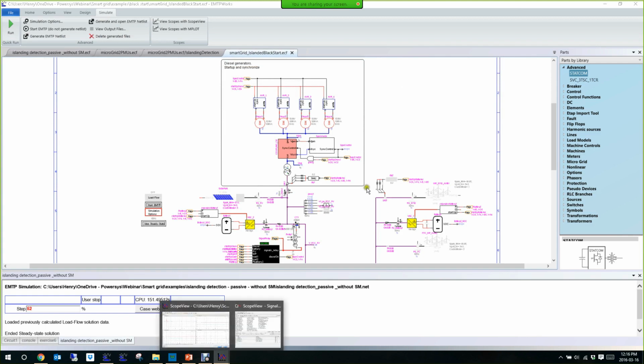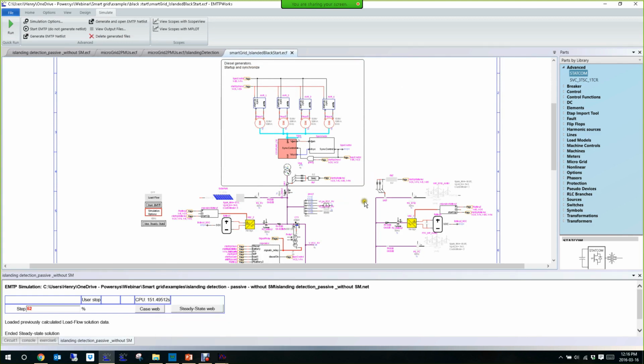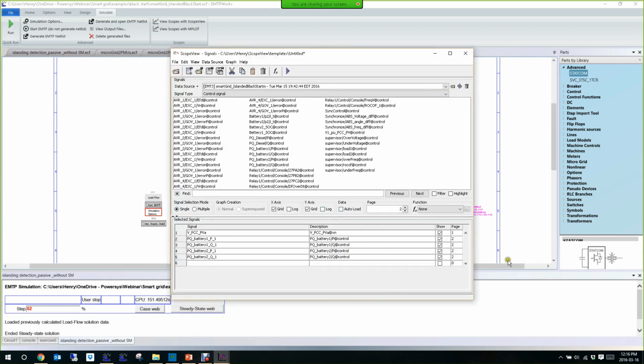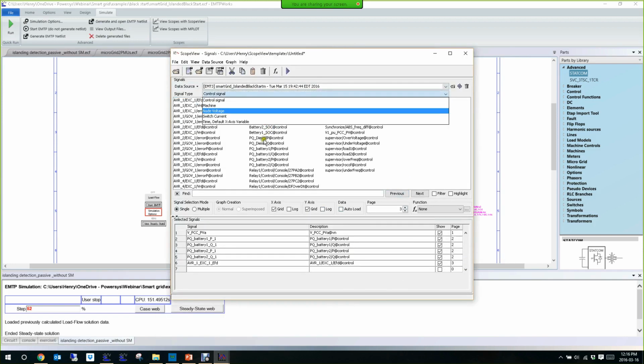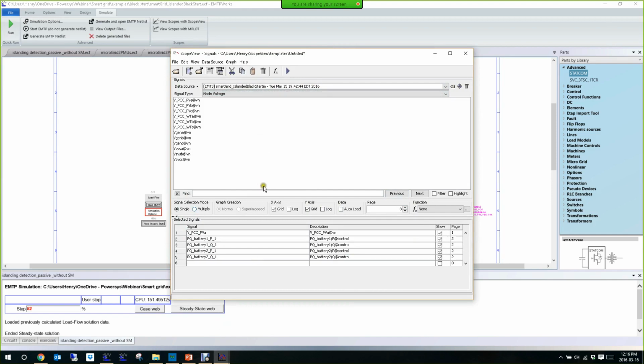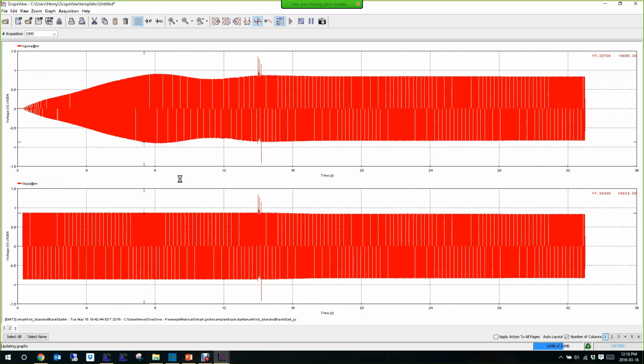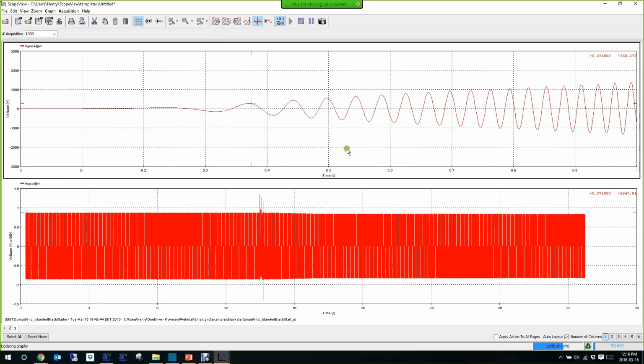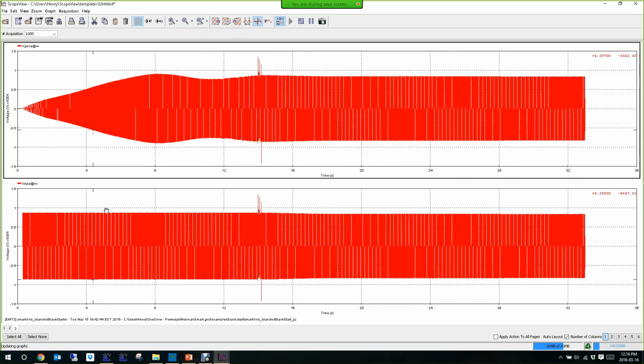So let's look at the voltage now of the machine and the voltage of the system, again only on phase A. I did something so that we can see the synchronization. You see that we start from 0. Initially we are at 0, then slowly the machine starts rotating, so the governor starts injecting mechanical power, and the field voltage also starts maintaining the voltage. So slowly we ramp, then we start reaching the steady state.